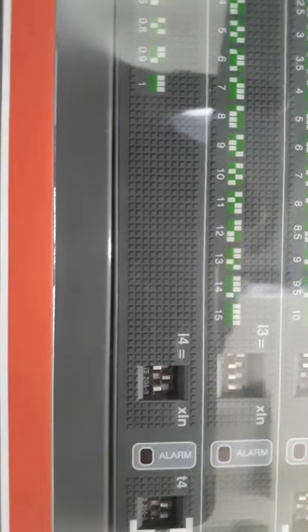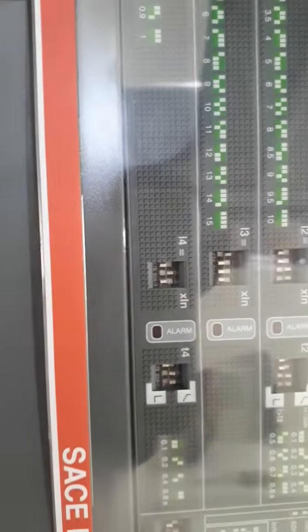This one is ground fault. Ground fault means, here there are three positions. First knob is in lower position, second knob is upper position, third knob is lower position. The value is coming 0.3. Okay, here see 0.3. So 0.3 into nominal current 1600 amps means around 480 amps coming. So when the ground fault current reaches above the set value, the breaker is tripping.